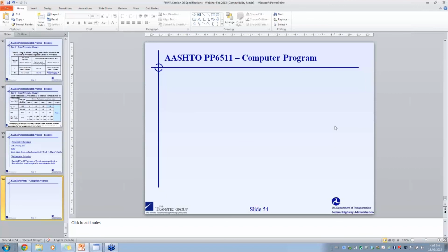Okay, next question is, are there any concerns with the elevated multi-laboratory precision allowed by ASTM C1260? Oh, I think there's concerns with the precision of any test. It certainly doesn't help the engineer where he's looking at results that are borderline around the limits of those test methods. Yeah, I think like any test, its precision is not as good as we would like it to be. All the ASR test methods that we run don't have great precision. I'm afraid they're not that repeatable.